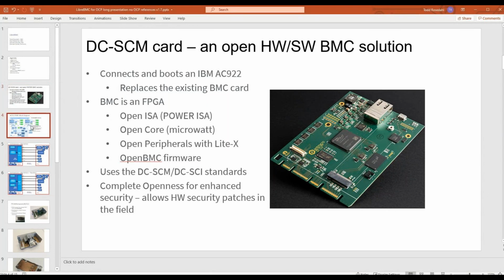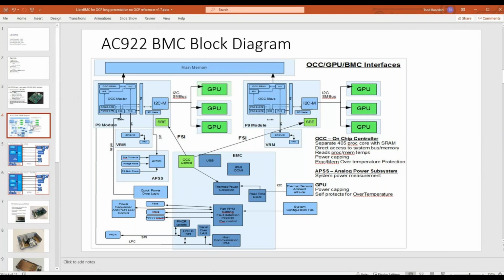Now, where we're at. Okay, so this is a picture I drew a long time ago that shows all the different connections that you have from that BMC in the middle out to the various components on the planar. So obviously you would expect all of this, right? Your fans, your power supplies, your VRMs, P-goods. You're getting your load via PNR. You got an LPC interface talking to the host. We have an FSI interface, which stands for FRU Service Interface. That has also been opened up. That was formerly not, but now that interface is part of the Open Power Foundation as well. That talks into that little self-boot engine. Anyway, much like you would have on an Intel or any other type of architecture, there are a lot of connections from that BMC card to various areas in the planar, but none of it is standardized today.